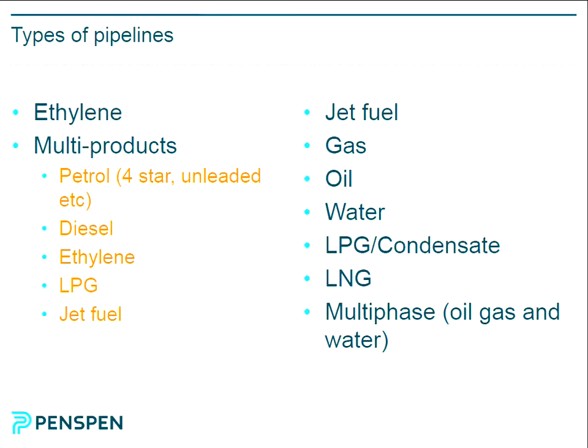So you do have to be careful transporting LPG in multi-product pipelines, because even vestiges of LPG going into atmospheric tanks can create safety issues. LPG is liquid at relatively low pressures, so you can transport it easily in a multi-product pipeline. But multi-product pipelines typically go between tank farms. If you then put LPG into your tank, or vestiges of it, you'll get gas forming and potentially some safety issues.